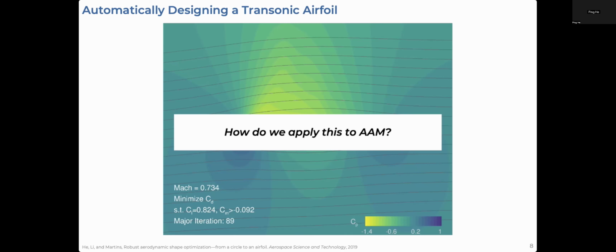For our problem, we're trying to leverage multidisciplinary design optimization, come up with a framework that is discrete adjoint based and uses DAFoam and some other tools to do design optimization for advanced air mobility vehicles. So we start with an optimizer, and the first step is always to define a geometry. This will parameterize our wing, our propeller, and perhaps some other parts of our aircraft.